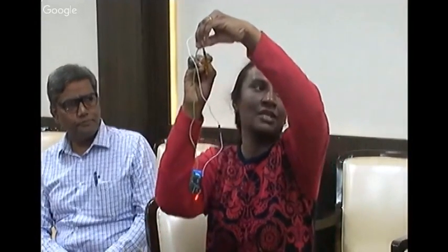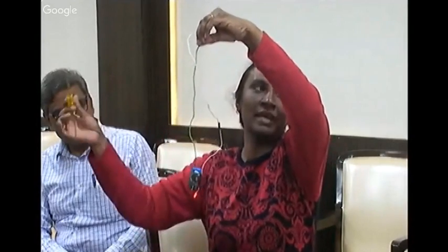So here now it is correct. When I am seeing, so now according to you, the right side is a cathode. Okay, so the center one is anode. This one is a gate. So now I'm just giving the gate pulse. Okay, so now it is glowing. Now I'm removing my gate pulse. Still it is in conduction. You can see here. Now you gave a gate pulse to it and now it has gone into regeneration. Until this battery is fully drained, it will continue in conduction.